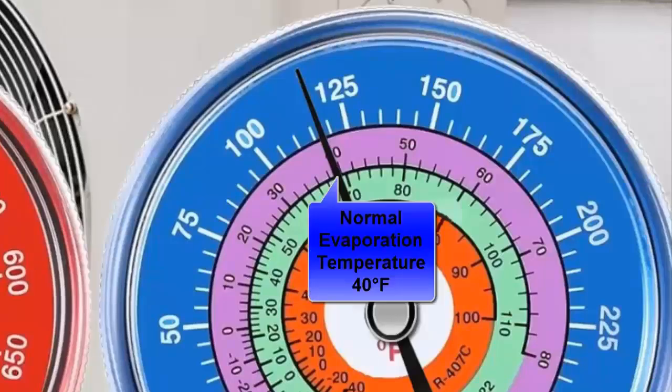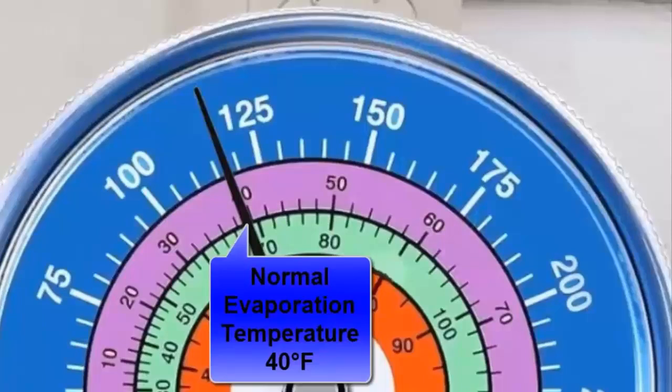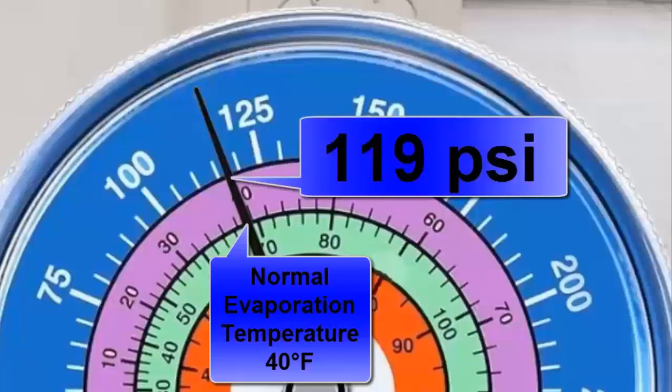The required low side pressure depends on the function of the system. For example, in a typical air conditioner, the evaporator temperature is kept above 0 degrees Celsius, since we don't want the coil to freeze. If we check a gauge for our R410A, a saturation temperature of 4 degrees Celsius, about 40 degrees Fahrenheit, corresponds to a pressure of around 119 psi.